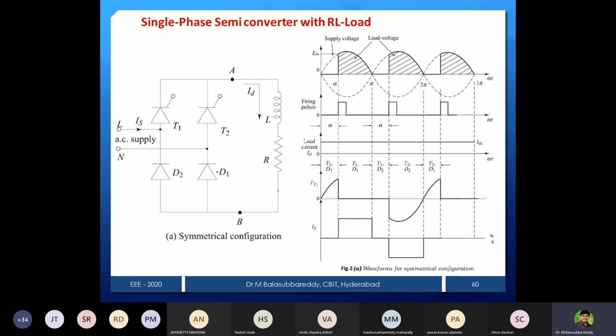Or if you are confused about how the devices are conducting, you can use it directly like this in the circuit itself. Now it is very fine. You can see now, the operation is just simple. It goes through T1 for the positive half cycle, D1 to out. Now energy will be stored like this, plus and minus, then minus and plus while it is discharging.